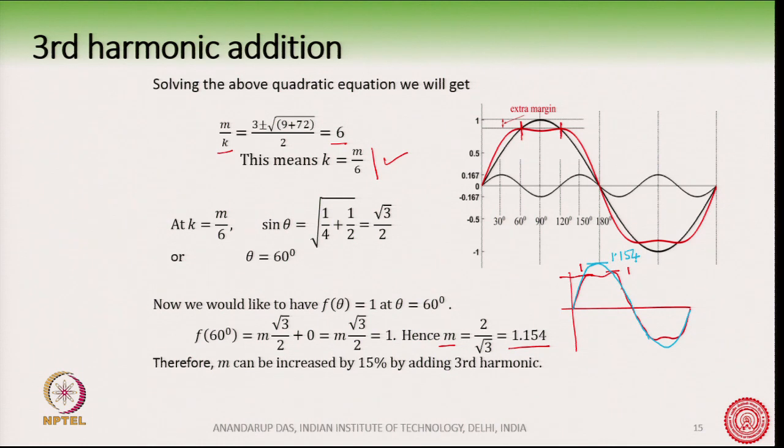inside the +1 and -1, because our carrier is inside here. This is where our carrier is. We do not want to go into over modulation, we will always keep ourselves between +1 and -1, but the fundamental is actually more than that. So, earlier we had also said that whatever is the fundamental voltage in the pole voltage appears across the load.